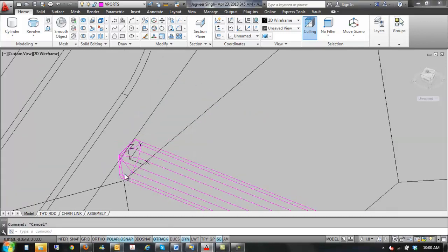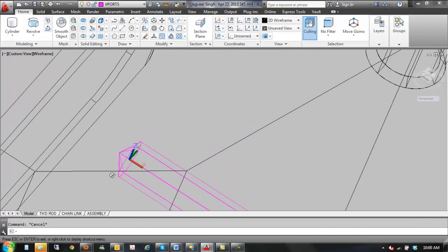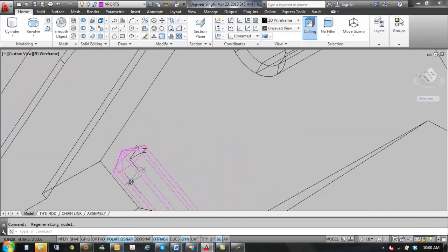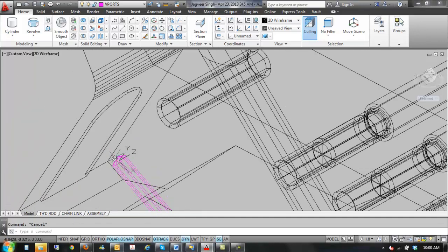So like in my drawing, like always I have got too many lines. I don't know why. Well, if you're revolving something that's not a closed polygon, it's a surface. It's like taking a line and revolving the line around. And when you do that, it adds all those lines. So you can visually see that, oops, it wasn't closed. Right? You got to make sure it's closed.